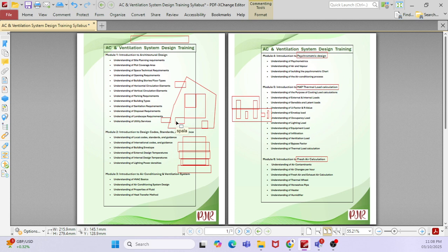Then when you go to the chilled water system, you will study water cooled chiller, air cooled chiller, cooling tower, and how to calculate and size the pipes and pumps. There are pumps and there is a performance curve, there is a system curve, there is an NPSH value, there is a power calculation. Then there is a building pump and there is a condenser water pump. So what is the difference, and what is the temperature? What is the on coil temperature? What is the chilled water temperature?